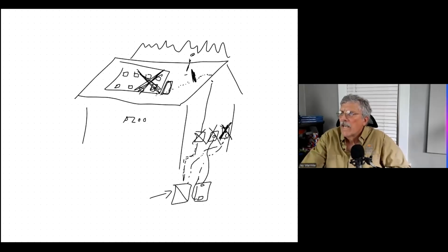So then SolarEdge came along and said, oh, you know what we could do is we could put all of the electronic devices, the rapid shutdown, the anti-islanding, the MPPT, everything that you've got in a microinverter, we can put it in an electronic device except for the inverter. We'll just keep the inverter down in the basement, but we'll put all these other electronics up here. So that became known as power optimizers. And those solved a lot of the problems, and you could make those for like $50. So it was an economic decision.